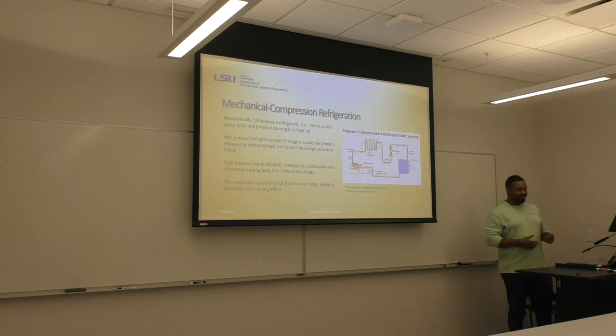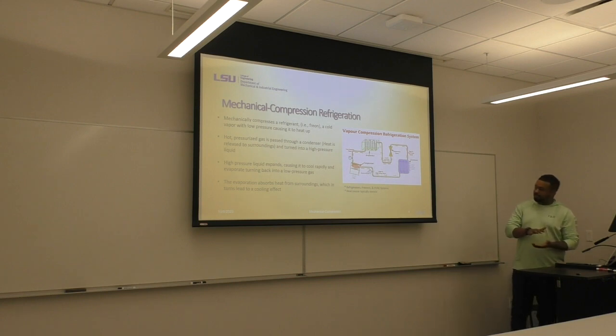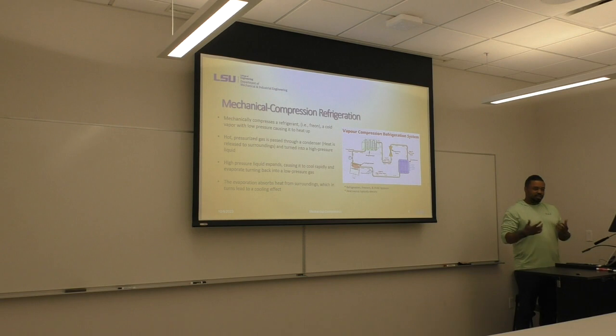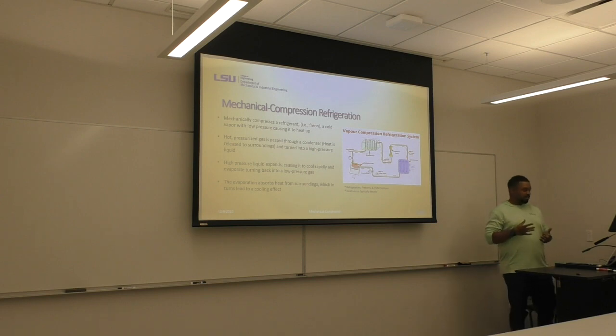So mechanical compression refrigeration is typically what we've been going over in these labs and doing research on. It's typically found in refrigerators, freezers, or HVAC systems, where we'll have a compressor which will compress your gas and excite the molecules and passes it along as a high pressure, high temperature vapor to a condenser, where the condenser releases heat to its surroundings, in turn turning that high pressure vapor into a high pressure liquid, which then